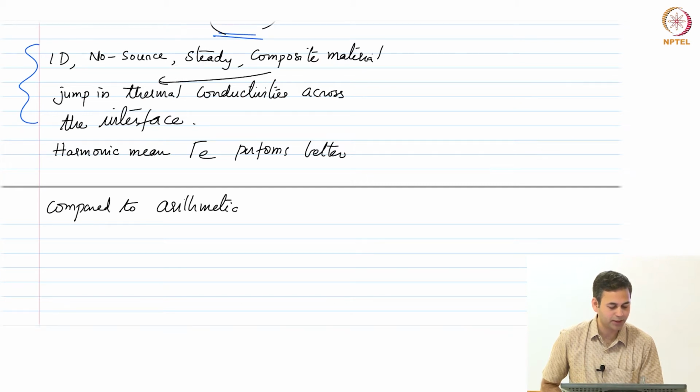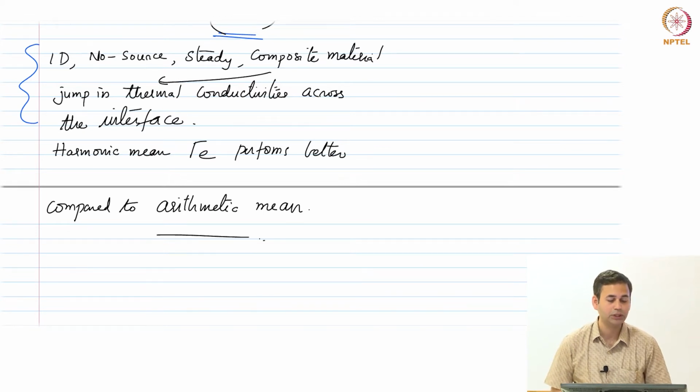Or essentially you get the correct result from gamma e, rather than from the gamma e from the harmonic mean rather than from the arithmetic mean. Okay. So, in general, if you want to obtain the diffusion coefficient on the faces, the interpolation by default would be the harmonic average. That is what you would use unless otherwise stated somewhere, fine.